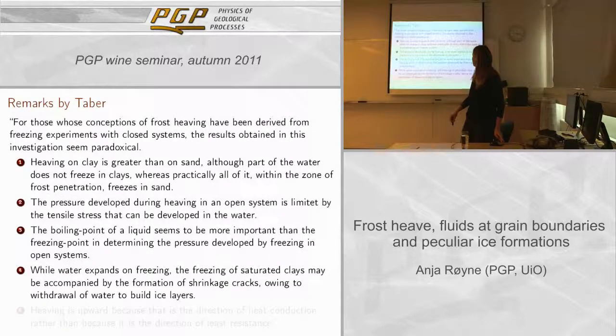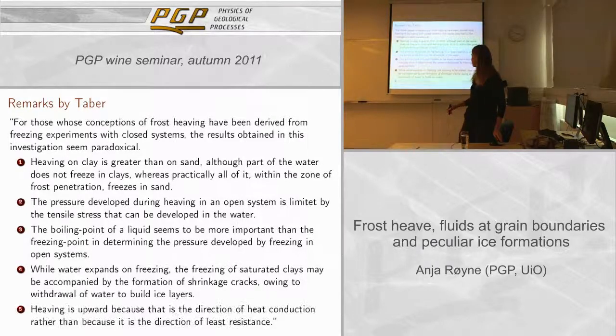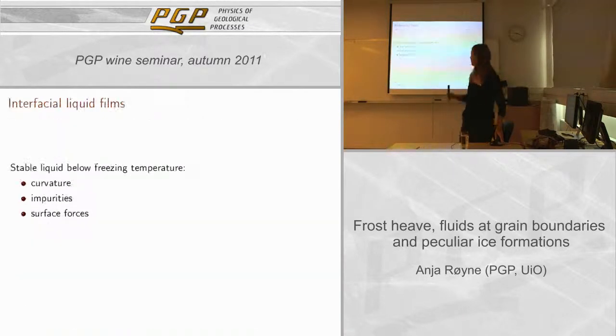And then while water expands in freezing, the freezing of saturated clay may be accompanied by the formation of shrinkage cracks due to this withdrawal of water to build ice layers. And then, as I said, the direction of heaving is not related to where we have the most resistance, but it's related to the temperature gradient.